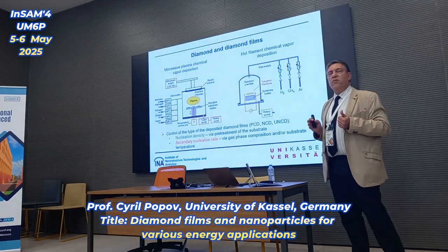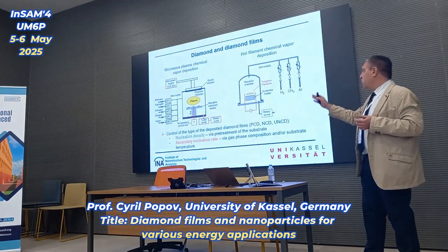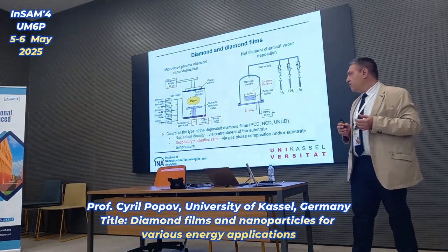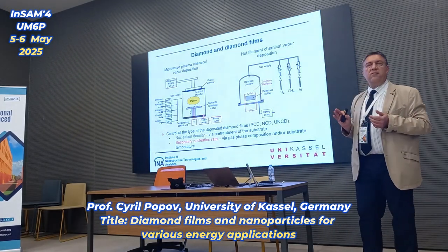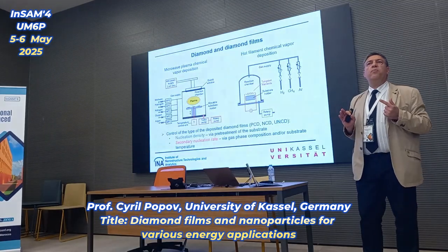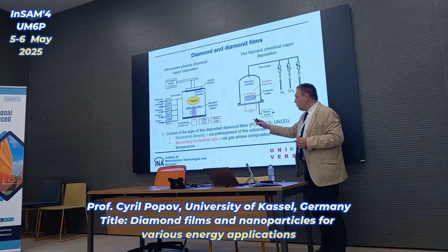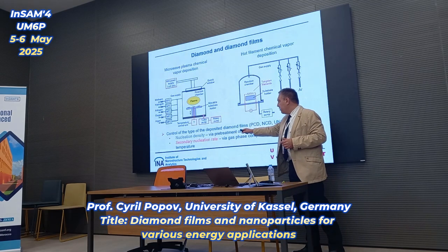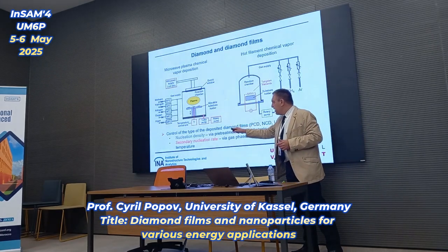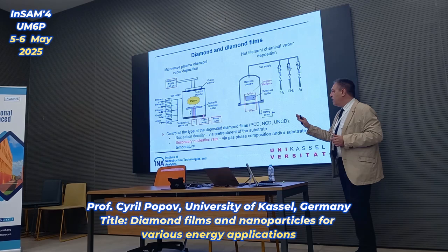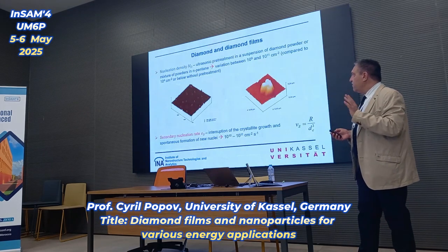This preparation plays an important role, because all of these three types of films that I showed you, poly-, nano-, and ultra nanocrystalline diamond films, can be prepared by both reactor types. But you have to vary two parameters to change the crystallinity. The first one is the so-called nucleation density, which is regulated by the pretreatment of the substrate. And the second parameter is the secondary nucleation rate, which is regulated via the gas phase composition and the substrate temperature. Starting with the first one, nucleation density.